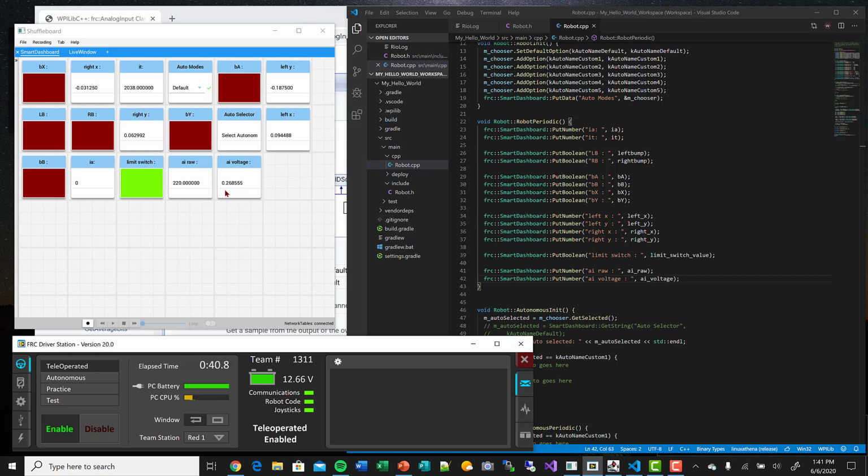I'm going to now attach the battery to the wires with my hands. So we got 1.4 volts on the battery, which is a converter count of about 1,000. On a scale of 4096 steps, we're at 1,165. 1.42 volts for this little AAA battery, and that's how you make yourself a little voltmeter. That's it for this exercise.